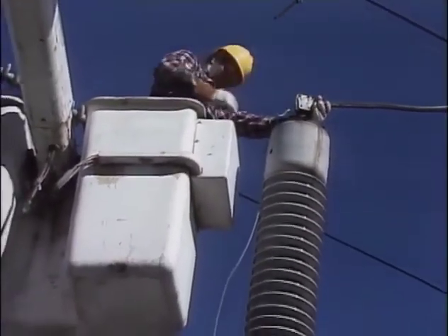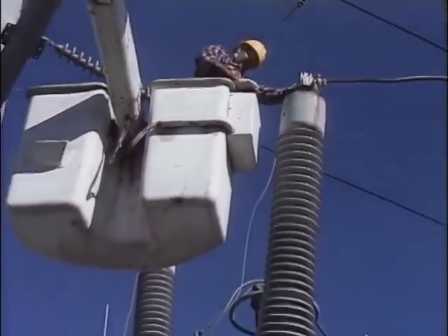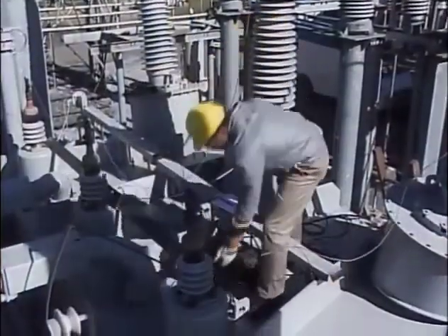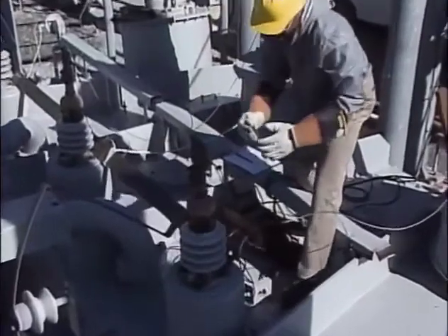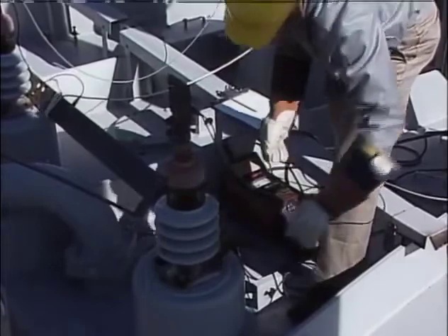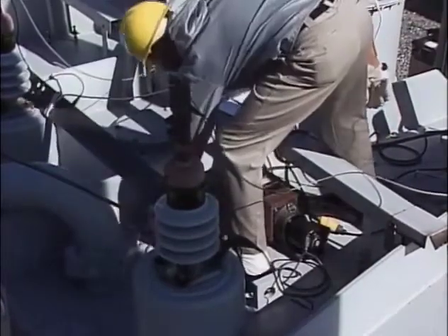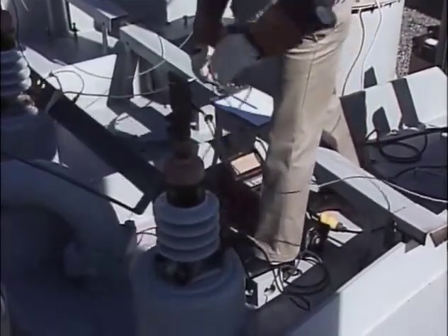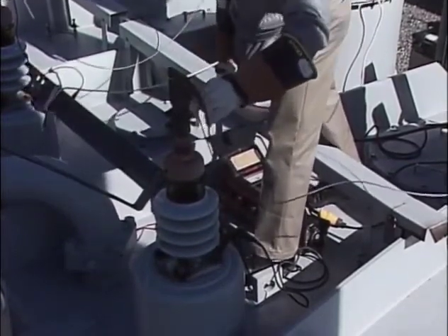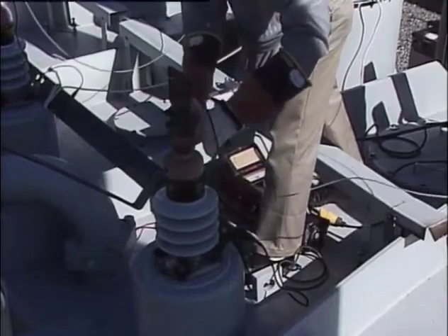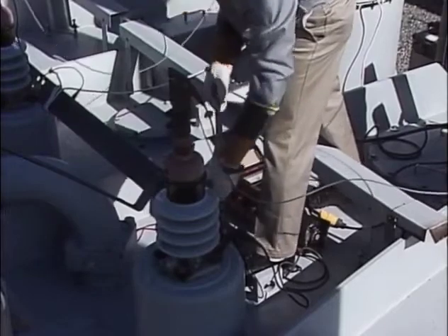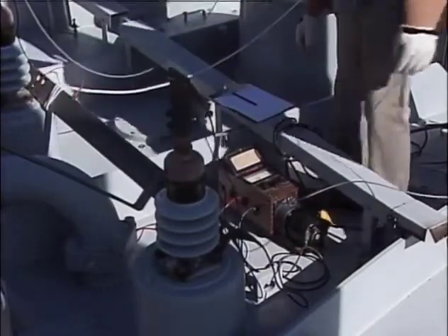Now, the megohmmeter can be connected to one phase of the reactor to test its insulators for that phase. The ground lead of the megohmmeter is connected to a station ground. Here, station ground is the ground bus that was disconnected from the neutral terminals of the reactor. The voltage lead of the megohmmeter is connected to one of the neutral terminals. Then the ground is removed from the neutral terminal. So now the megohmmeter is connected to station ground and to the shorted terminals of one-phase coil of the reactor.